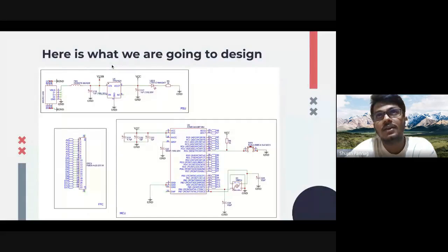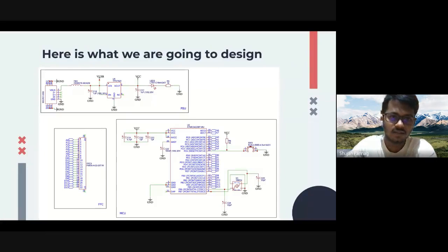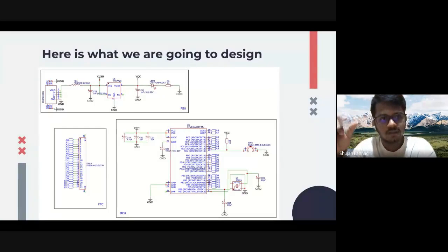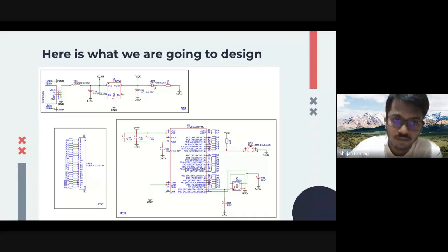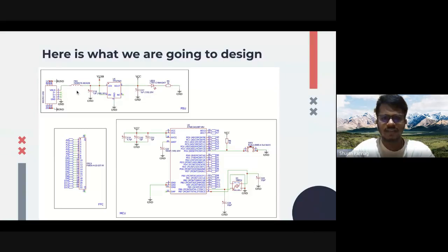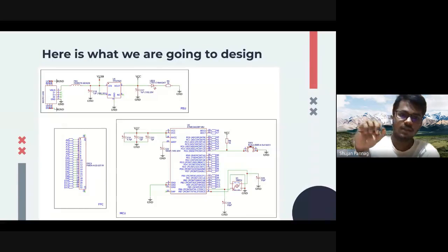It's like an inductor, like a parallel LCR circuit with another series resistance. The way you find it on the market is, you get a ferrite bead like a 100 ohm ferrite bead. What that 100 ohm suggests is the series resistance when you model it as an LCR circuit. What it actually does is, it's basically a low pass filter, but with a very high roll off. If you do the Bode plot, or see the frequency versus the magnitude of the output, you get a really high roll off.